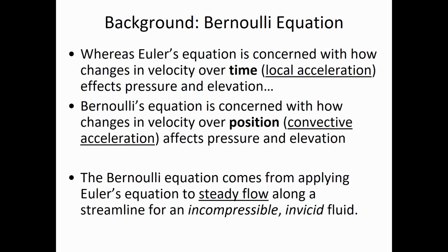So as long as we keep in mind that there are limits to Bernoulli's equation, we can still be successful with it. It's still useful, but it's never going to be perfect. It's never going to perfectly describe what we observe out in the world. And so when we get into the lab and we test Bernoulli's equation, it's not going to be one of those labs where you have 1% error, because we're going to be using it with water, and water has viscosity. And so one of the weaknesses of Bernoulli's equation is it doesn't account for friction losses. And that's what this whole discussion of viscosity is all about.